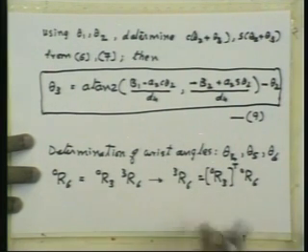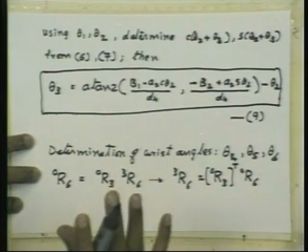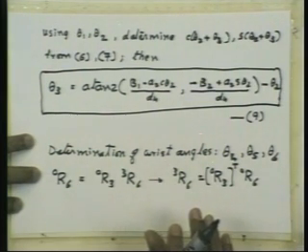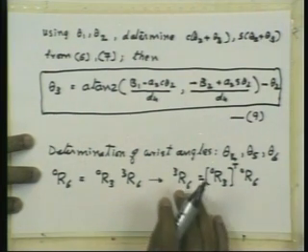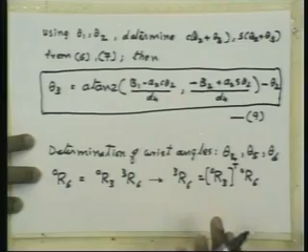We also have the expressions for the 3 matrices which get multiplied in order to give us this. So we can express the elements of this in terms of theta 4, theta 5 and theta 6, right. So each element of this matrix can be expressed as a function of theta 4, theta 5 and theta 6, and we know each of those elements numerically, okay. So that particular expression for the matrix, you can multiply out those linkage transformation matrices and you will find the following.